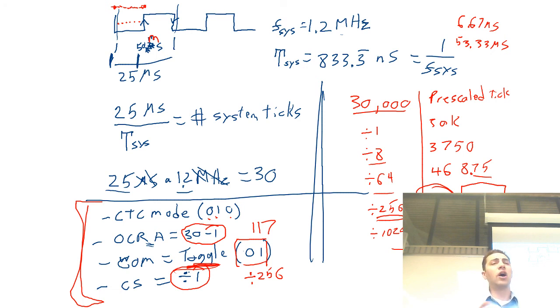The only sort of offset you might see is because of the calling overhead, right? You have to call that function, so you need a call instruction. Whereas an interrupt doesn't get a call instruction, but it does change out all the program counter stuff. My guess is at the end of the day, it might be 1 cycle slower one way or the other. The answer to that question is contained within the data sheet. You just have to read a little bit more on how interrupt service routines are handled at the processor level. Okay? I don't have that information rolling around in here right now. All right, that's fine. Other questions?